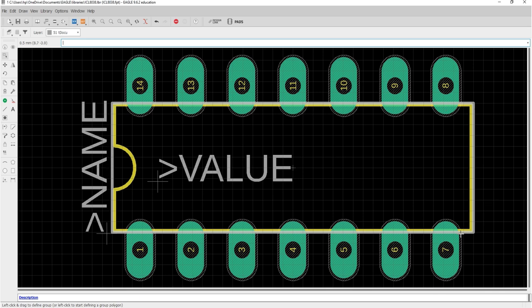The package dimension is the rectangular gray outline that you see connecting all of the paths. This outline represents the actual physical dimension of your part, which can help during your PCB layout process to see if you're placing components too close together. Then, there is the silkscreen outline. The silkscreen outline is the rectangular yellow lines lying over the gray package dimension lines.